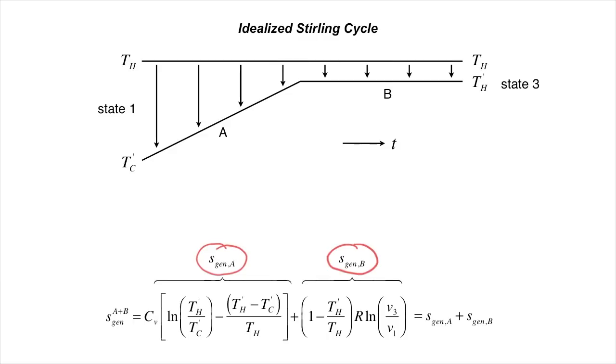In the Carnot cycle, we never actually heated or cooled the gas to change its temperature. The temperature changes were all done adiabatically, so that all heat transfer could be done isothermally, at the reservoir temperature. But here this gradient is an inherent part of our process, so there's nothing we can do to engineer it away other than choosing a different process.